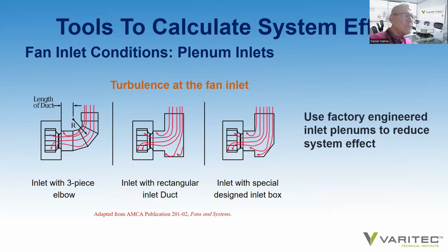Consequently, I suggest, certainly for utility vent sets in those conditions, work with the fan manufacturer that's being laid out as basis of design. The fan manufacturers that I've worked with can provide inlet plenums that are designed in a way that actually minimize static system effect at the inlet of a fan.